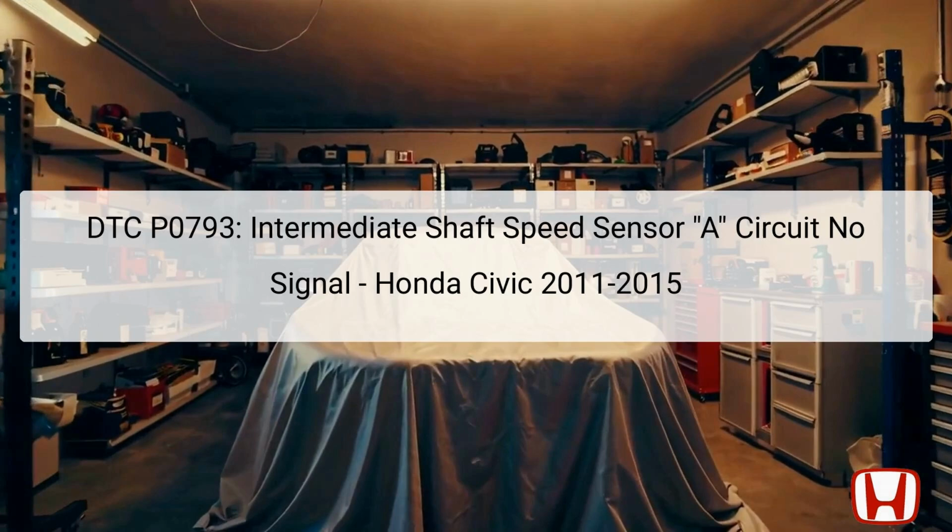The Diagnostic Trouble Code, DTC P0793, indicates an issue with the intermediate shaft speed sensor A circuit. This code specifically signifies a no-signal condition from the sensor, which is crucial for the operation of the continuously variable transmission, CVT. The intermediate shaft speed sensor is located on the CVT drive pulley and monitors the rotational speed of the intermediate shaft.